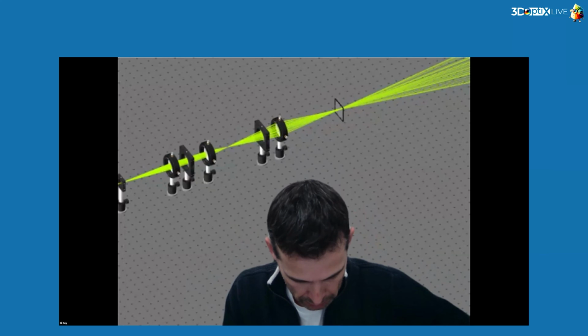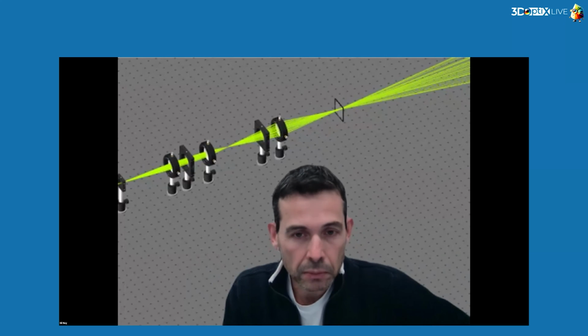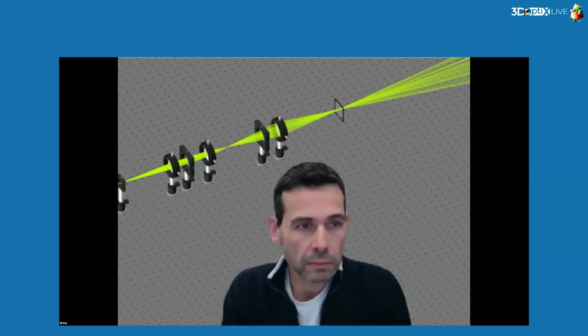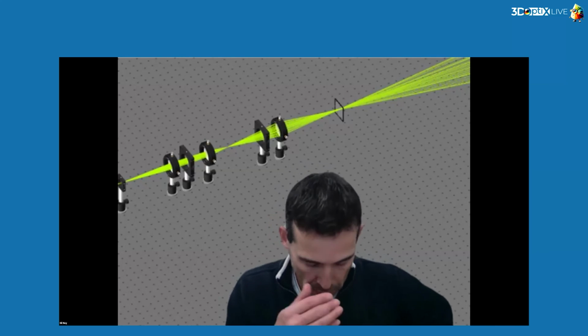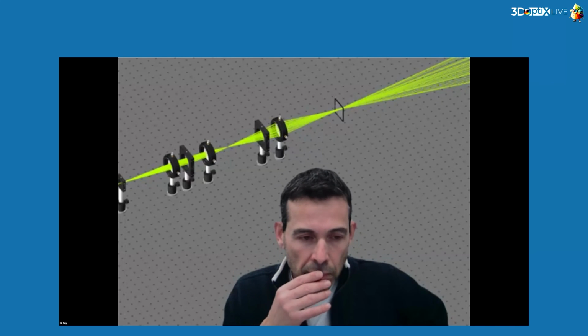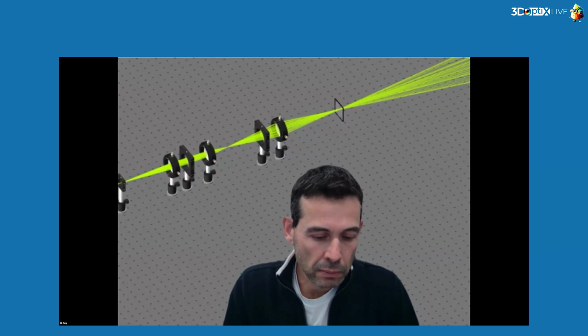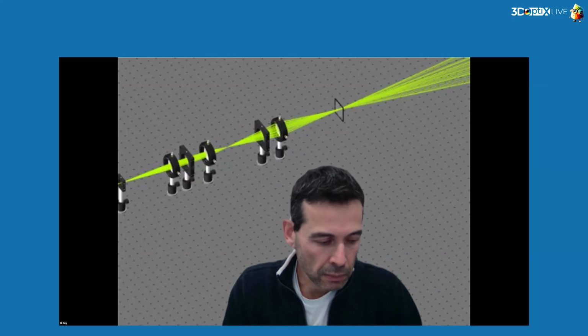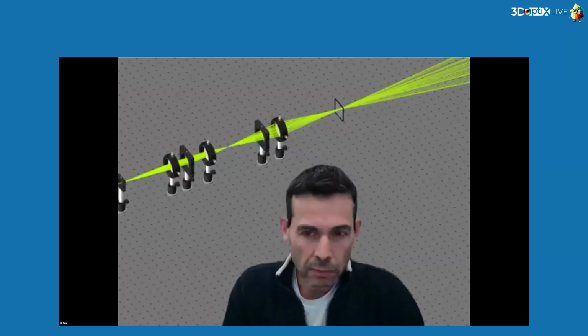In most software packages, if you have a light source that doesn't have any symmetry, you're going to have to use a multitude of light sources to simulate that. Generally, with an LED, we assume it's symmetric about the optical axis. Now, if you did have an LED that had some hot spots and cold spots, you can definitely simulate that with a few light sources and possibly even some lenses or a mirror to get the output that you really want. So it's a little bit more complicated if you don't have that symmetry, but it's definitely possible.